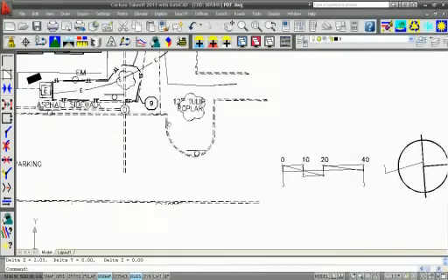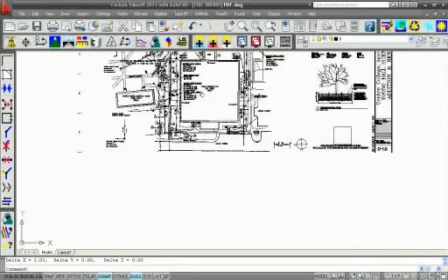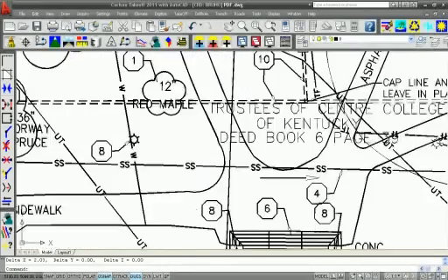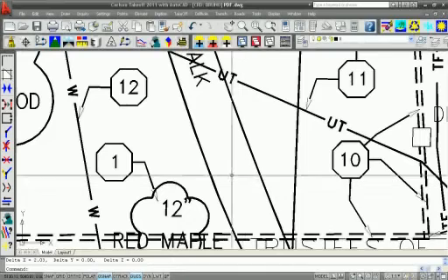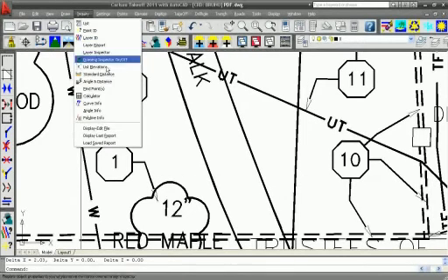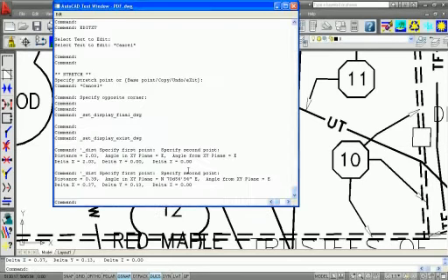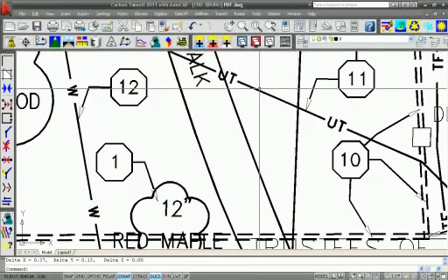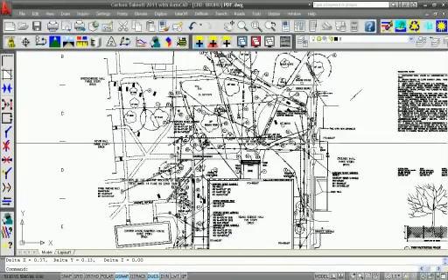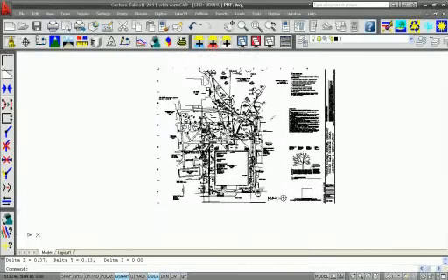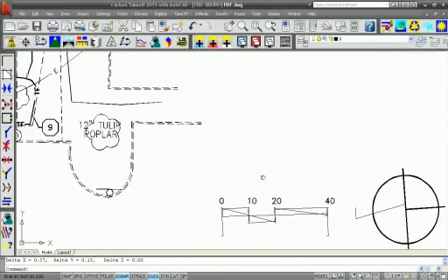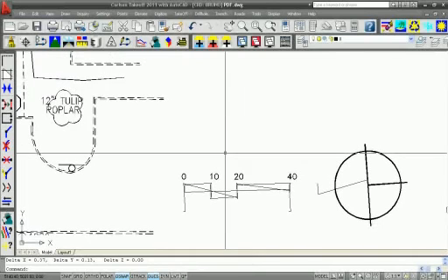So obviously the scale is wrong in here. All my volumes would be way off. Just to get an idea, this asphalt sidewalk here, if I ran that same command, standard distance, across here, it's saying that sidewalk is less than half a foot wide. So obviously that's incorrect. We need to rescale this drawing in order to get accurate quantities on it. Question. Yep. You'll probably most likely have to do this with every PDF file that comes in.